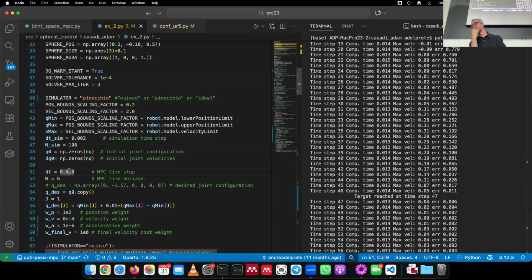It can maybe be numerically not stable. Yeah, that's true. If you have a kind of unstable system to integrate, having a larger time step can make it more unstable. But even if it's not unstable, like in this case with 20 milliseconds, I don't think it would be unstable. It's just less accurate, the integration.